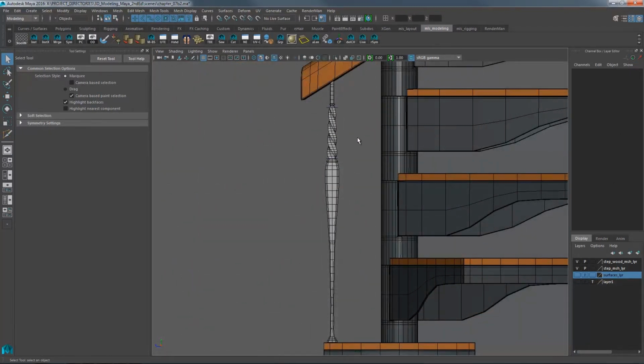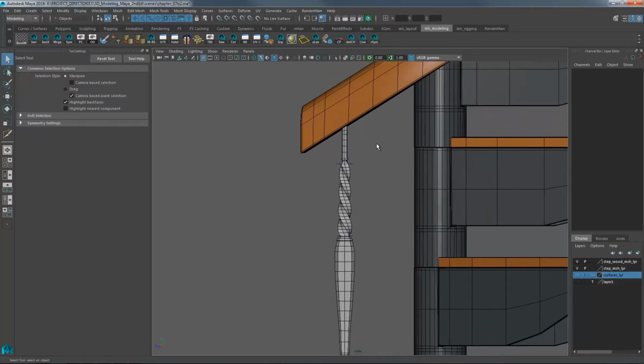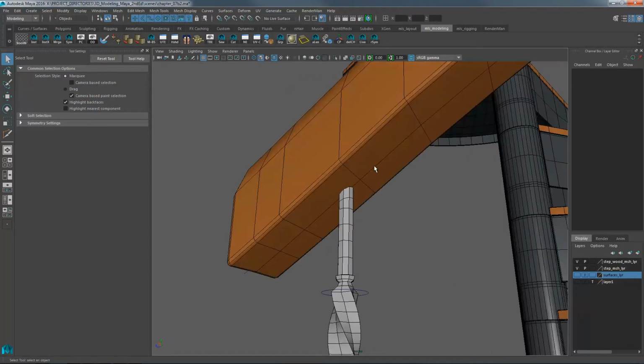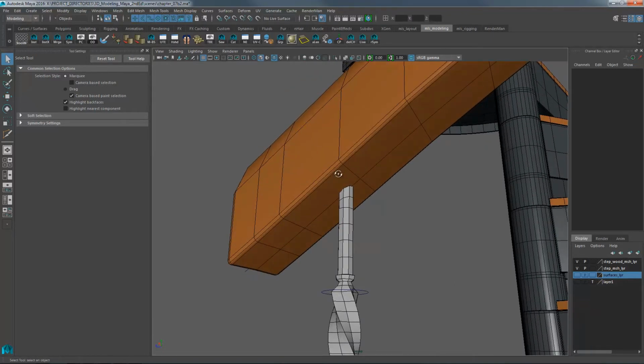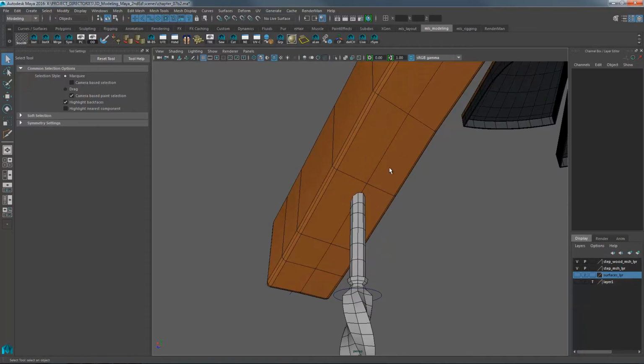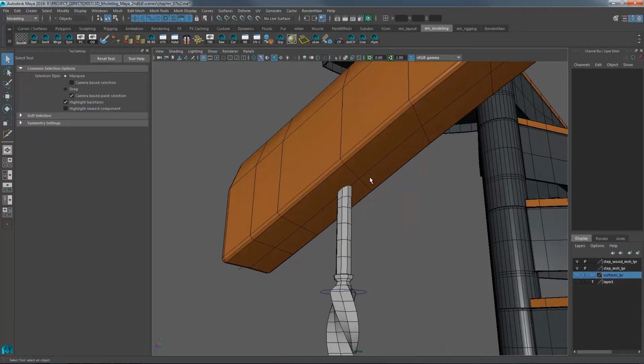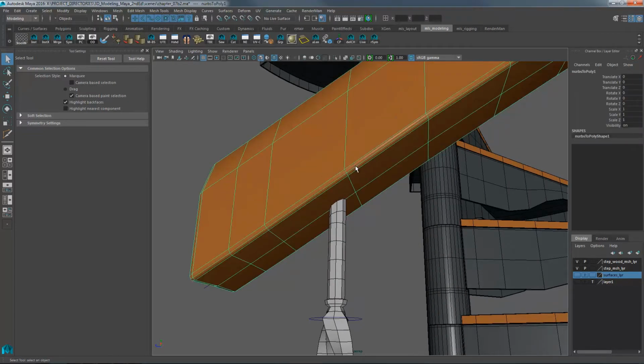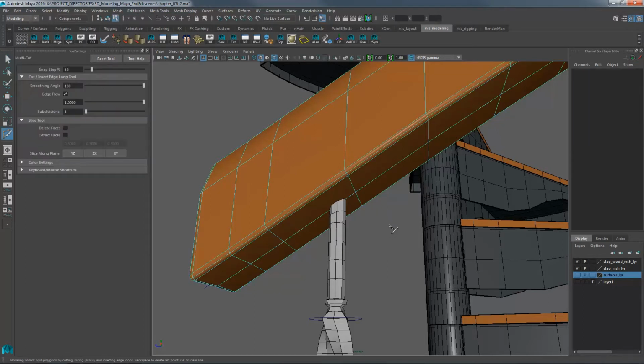All right, I finished the twist, and I'm ready to add that little metal tab at the top of the banister. I think the way I want to do this is to use the edges to guide me on fitting it exactly against the surface there. Just a little broad, flat box that sits up there that I could connect the banister to. And I'll add edges to the handrail for this process, then take those edges out when I'm done with this process. And I'll make sure that my edge flow is off when I do this.